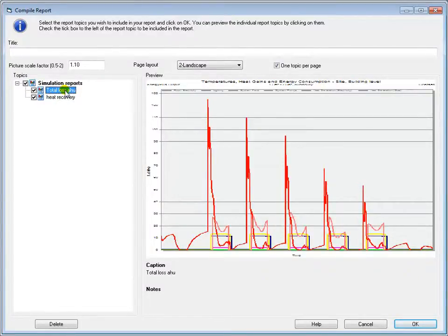The comparison also highlights that there is almost no change in the gas consumption of the hot water loop, as this is meeting the base zone heating demand, whereas the AHU coil is only being used to meet the load created by the ventilation air.